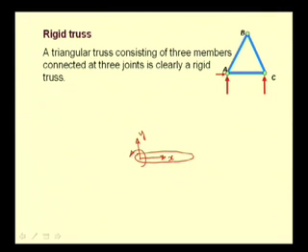So, each two dimensional element has 3 degrees of freedom. So, if we connect another member, let us say the first member is AC and we connect it with another member CB, then 2 of its degrees are arrested.